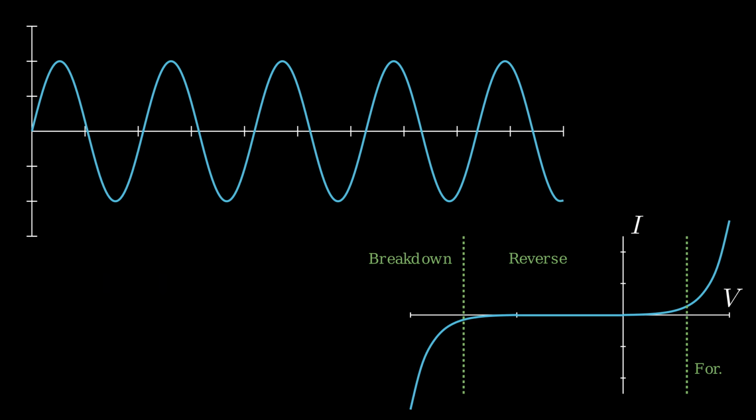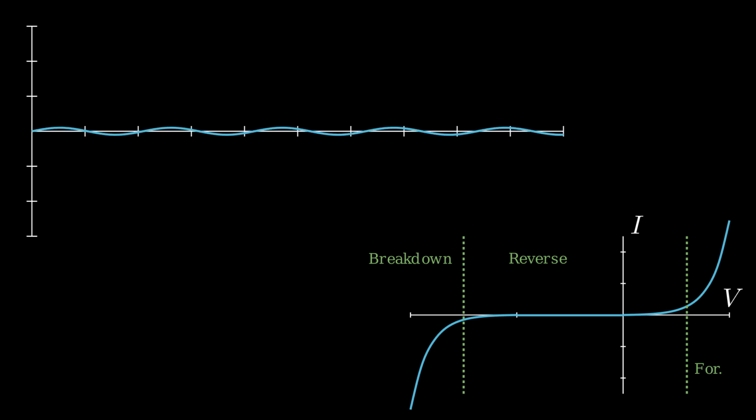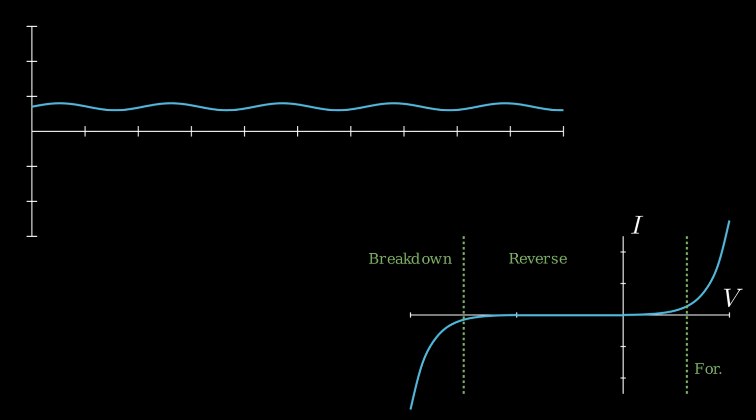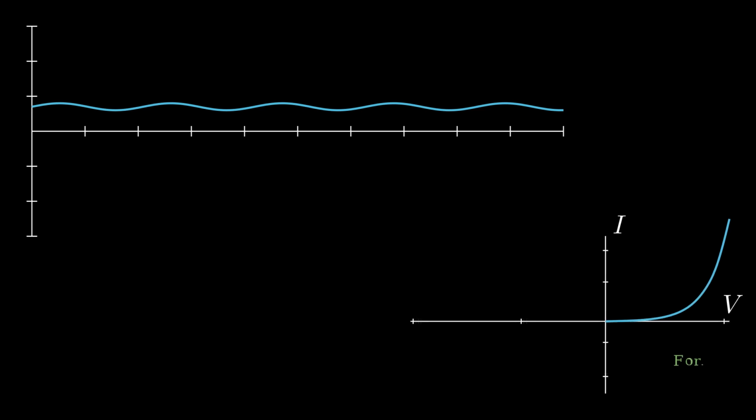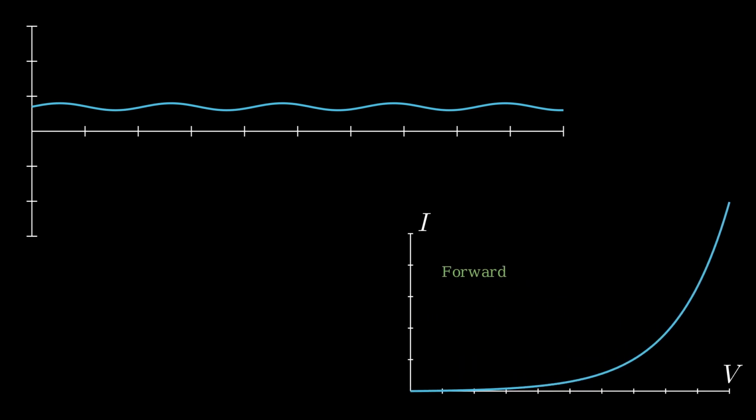For small signal analysis, we can take a different approach. Even if the signal gets small, we do not avoid the transition between regions. To avoid the transition, we add a DC offset to the signal. As the diode is only going to be forward biased, it is worth focusing the VI plot on that region. The DC offset causes the operating point to be centered around a value away from the border of the forward and reverse regions. When the AC part of the wave is not included, we say that it is quiet, or quiescent. Quiescent point frequently gets shortened to Q point.